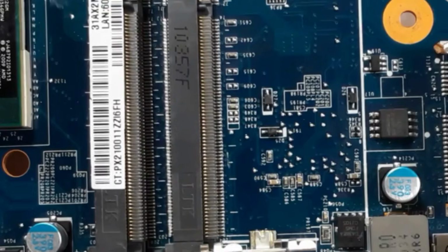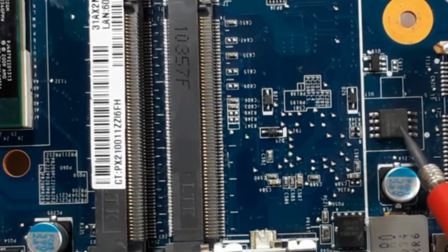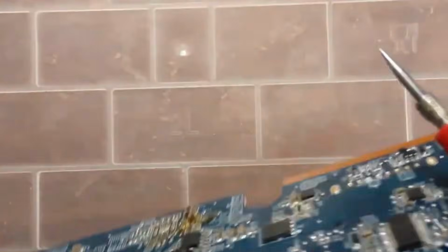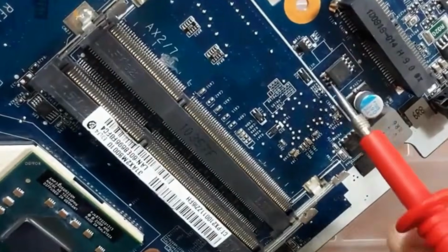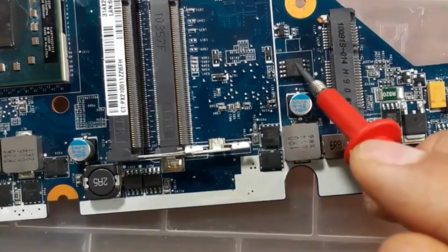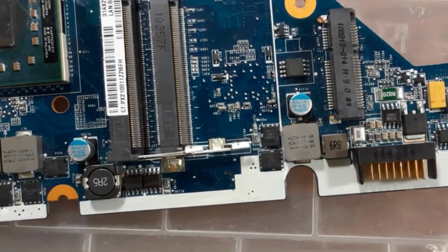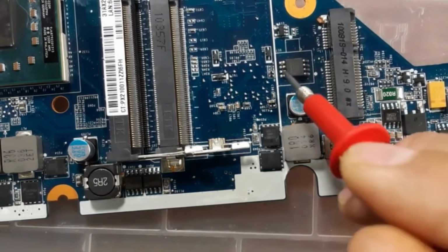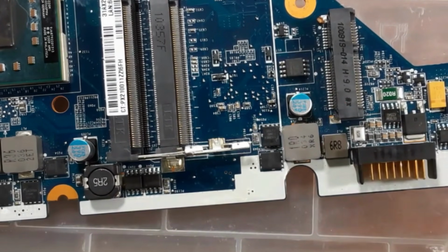Okay. So what you should remember is that the BIOS chip is always near the ICH or the Super I/O. As you can see here, we have the Super I/O. Directly under the Super I/O, as you can see, we have the BIOS. Okay. The 8-pin BIOS that is used frequently in motherboards is composed of 8 pins. Always pin number 4 is connected to the ground and pin number 8 is connected to the VCC.